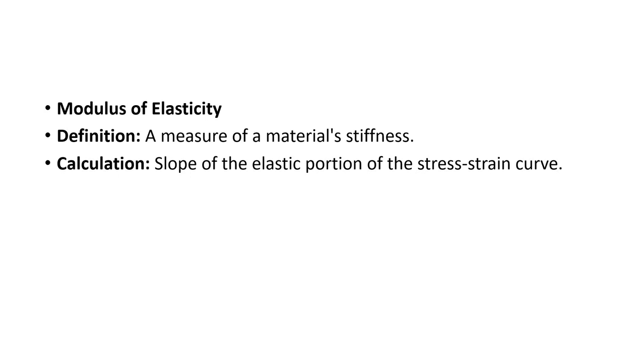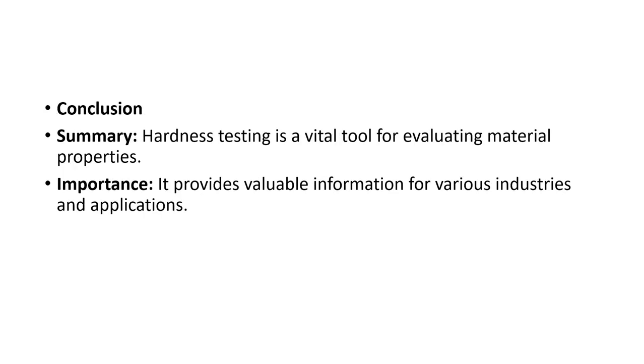Again, it is very important to calculate the modulus of elasticity, and the modulus of elasticity is nothing but a measure of a material's stiffness, and it is calculated from the slope of the elastic portion of the stress-strain curve. We already studied this in tensile testing.